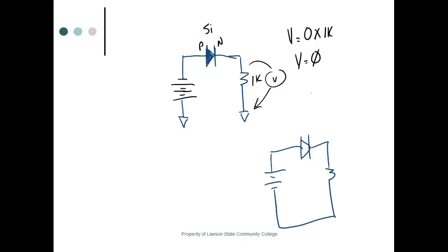And with our meters, that's what we'll see. If that was a 10 mega ohm resistor, we might see 600 millivolts because there is leakage current going through there. Understand that, but it's so small, with our standard resistors we won't see it. 10 mega ohm is practically an open circuit, right? You understand that. But there is current flow through there. So we'd measure about 0 volts.